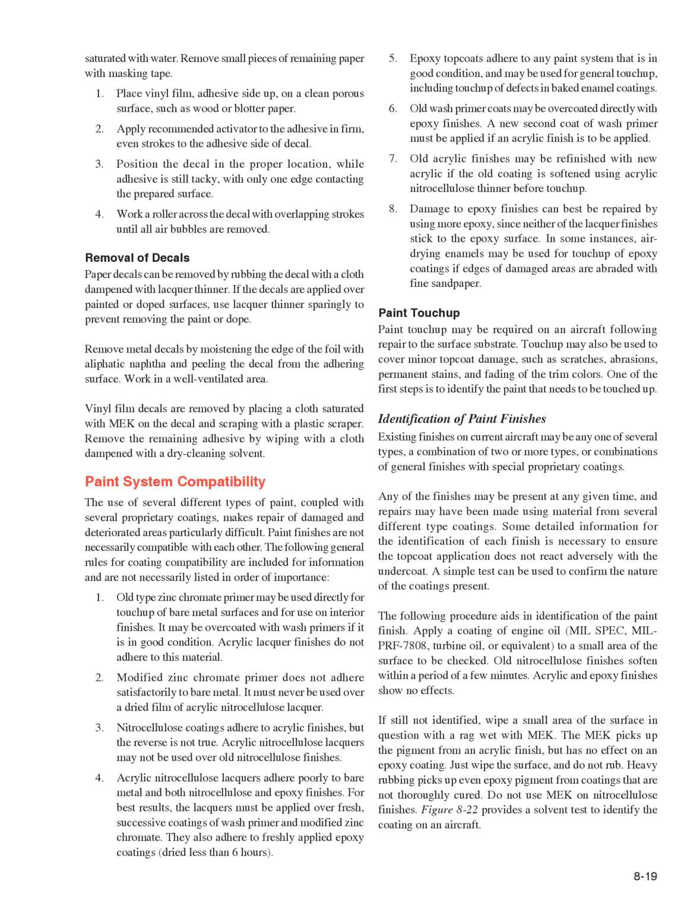6. Old wash primer coats may be overcoated directly with epoxy finishes. A new second coat of wash primer must be applied if an acrylic finish is to be applied. 7. Old acrylic finishes may be refinished with new acrylic if the old coating is softened using acrylic nitrocellulose thinner before touch-up. 8. Damage to epoxy finishes can best be repaired by using more epoxy, since neither of the lacquer finishes stick to the epoxy surface.